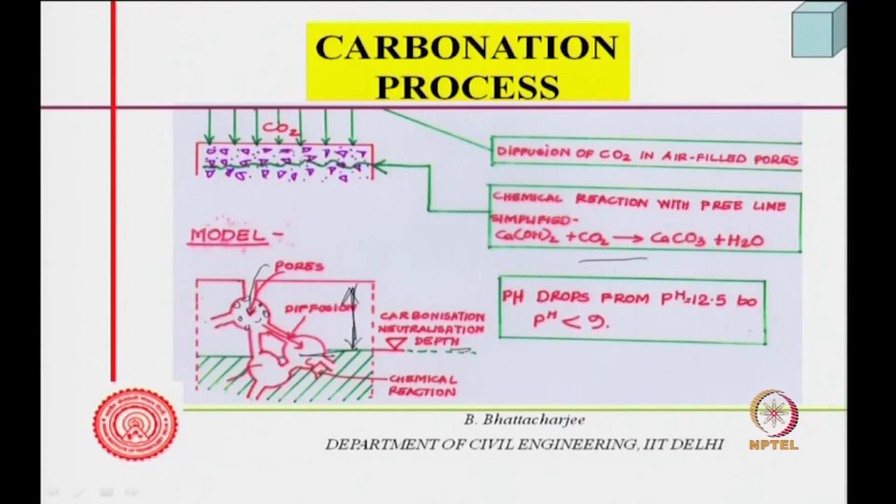is finished, we call it the carbonation reaction has occurred, carbonation neutralization. So, this is the neutralization depth, and that is the carbonation depth. So, up to which carbonation depth, all the alkaline material has got neutralized by carbon dioxide coming from outside. So, again the pores are important, moisture situation is important.